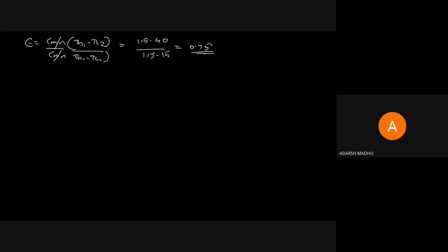So the third question is to find the surface area, using the NTU method. What is the equation for surface area? I said that the equation to use is NTU equal to UA by C minimum. So the area equals NTU into C minimum divided by U. This is the only way to find the value of area here, so you want to find the value of NTU.